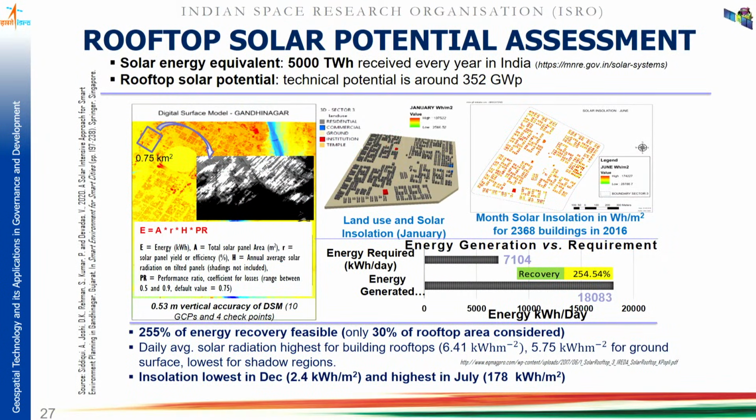Then we have also used this remote sensing imagery to do rooftop solar potential assessment. If our built up area is this much, what is the sunlight and what is the insolation, basically. So we have tried to find out how much rooftop solar potential there is for various areas, so as to ensure sustainable development. This DSM which we have made, you can make using high resolution remote sensing products also, or from ground survey you can make a DSM also.